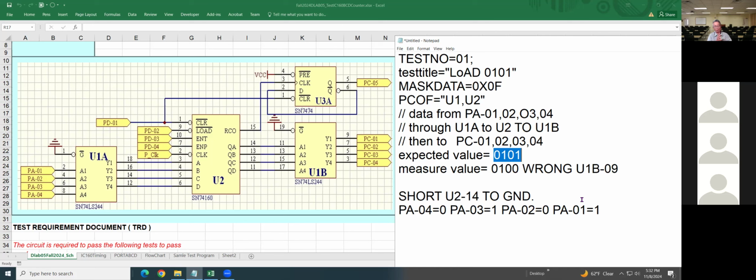Okay, two ways of troubleshooting. One way, you can go from input to the output. You know it's wrong on the 14 here. That means you can go in from PA pin 2. Logic 1. Okay, you go to pin 18. Logic 1. Okay, you go to pin 14.